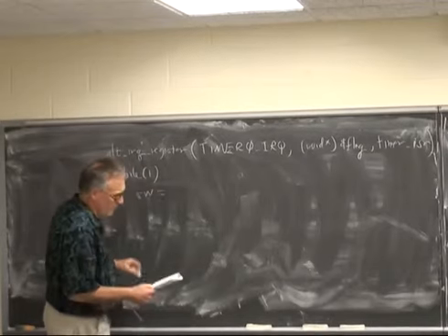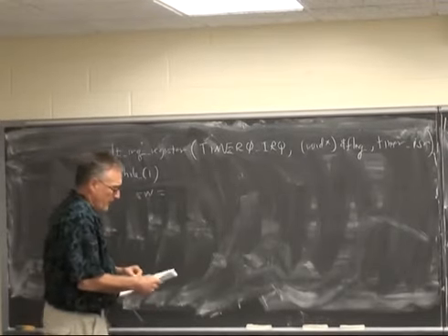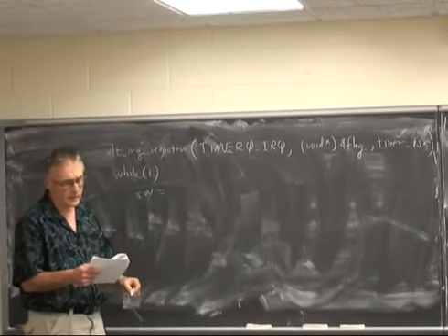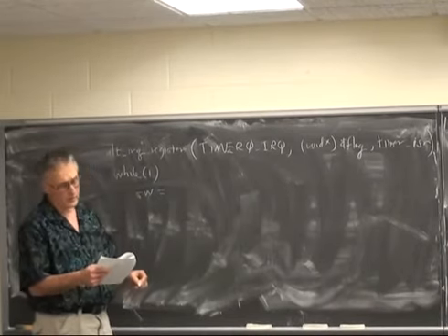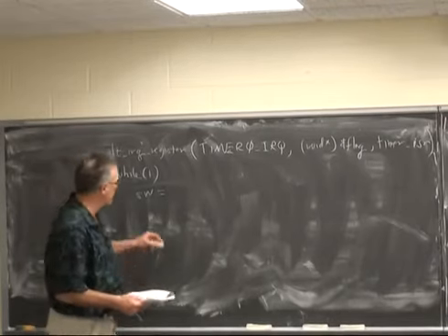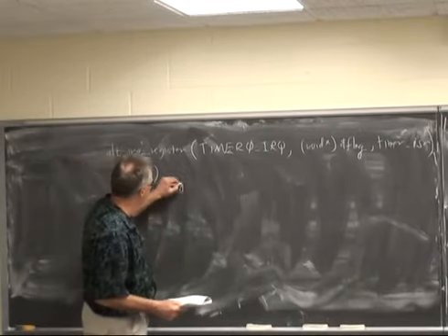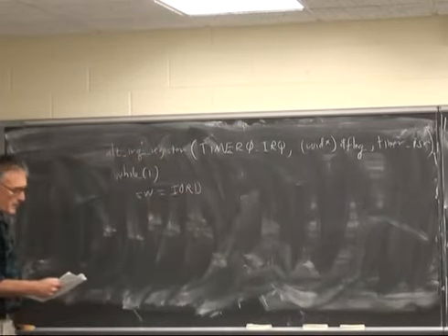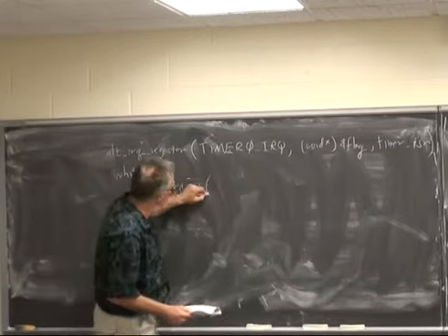So our switch variable, I could write this as IORD_ALTERA_AVALON_PIO_DATA of IN0_BASE, but instead I'm just going to write this as IORD, for IO read.